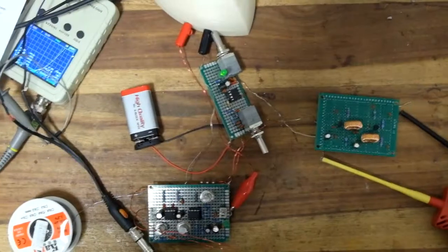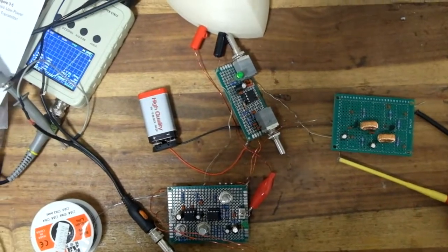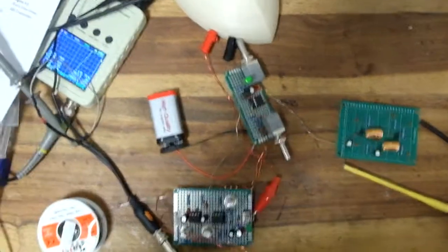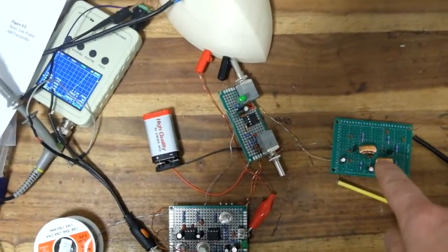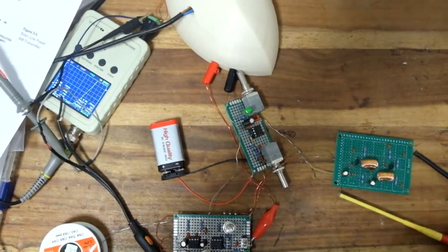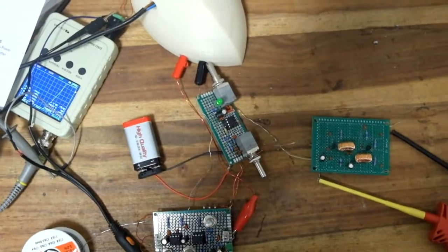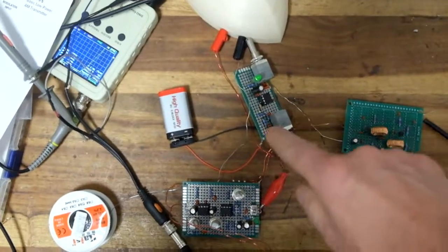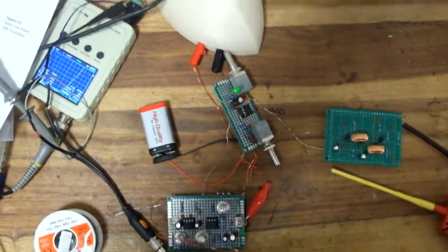For that reason I tuned the scope in a way that you can see the waveform, and you will see the peaks and the valleys. I now modulated the waveform with a signal that is generated here from the basic low power AM transmitter, and it generates a carrier wave upon which the tone, the signal I generated before, is put upon, so to speak.